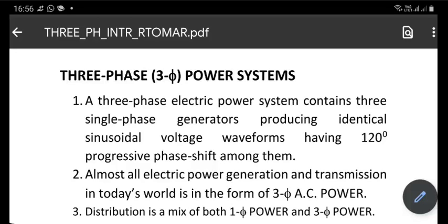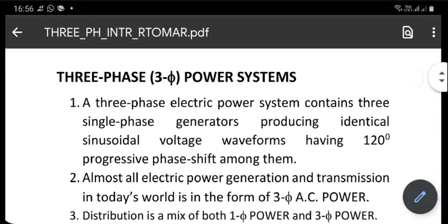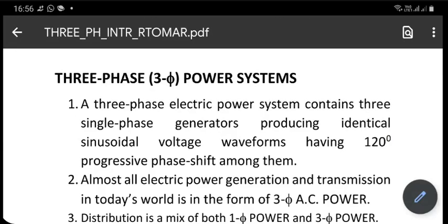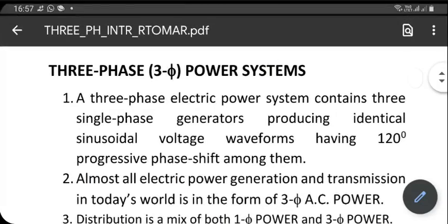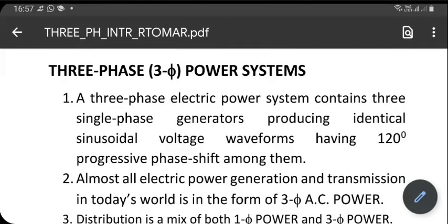Other advantage of three-phase systems compared to two-phase systems or single-phase systems is that if you do everything right, the oscillatory part of instantaneous power may be made zero, in theory at least. Remember, in single-phase systems, I showed you the instantaneous power having a constant term and a time-dependent term. That situation is very dangerous, as I told you several times. That can actually be avoided in three-phase systems if you do things right. It's not easy, but theory allows it. In single-phase systems, even theory doesn't allow it. So let's look at this document.